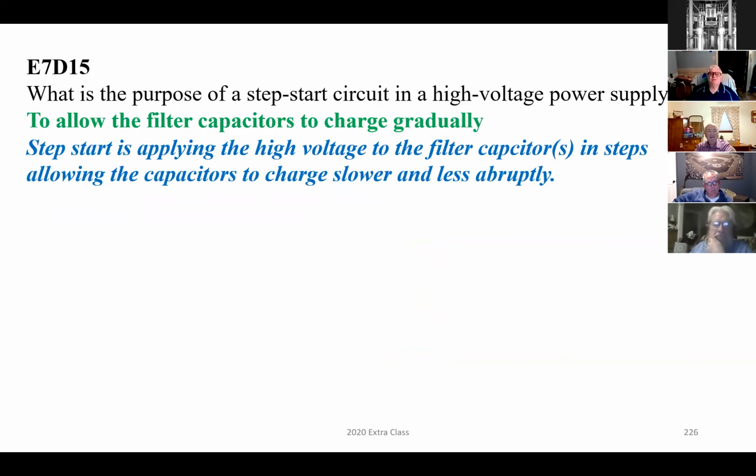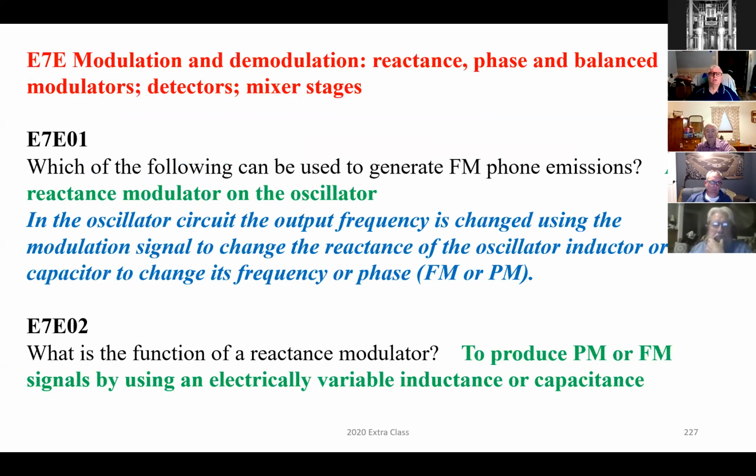All righty. What is the purpose of a step start circuit in a high voltage power supply? It allows the filter capacitors to charge gradually. Step start is applying the high voltage to the filter capacitors in steps, allowing the capacitors to charge slower and less abruptly.